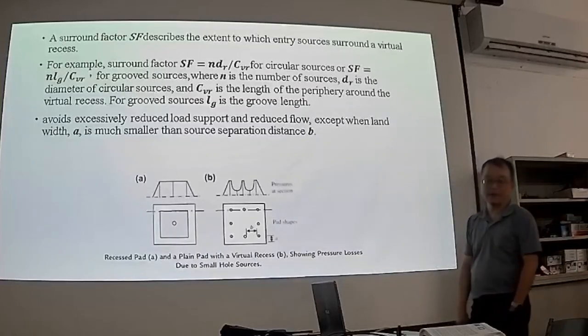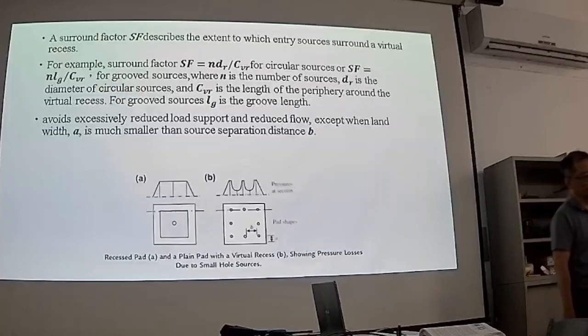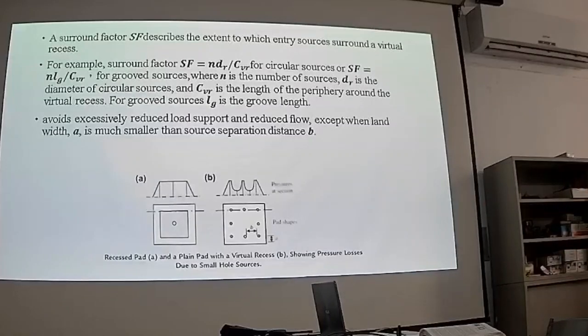Because for your machine tool, you have multiple recesses. And for each bearing you need to have 8 connections of the oil pipe and restrictor. For multiple ones, you have a lot more oil pipe connections and restrictor connections. So it's really not practical to do this. Okay?